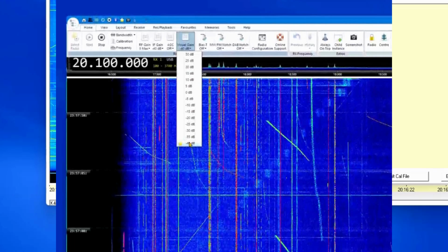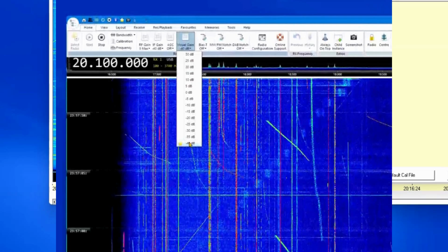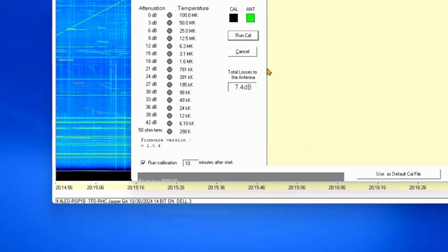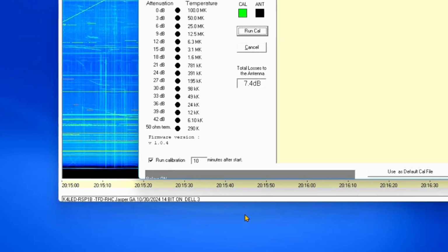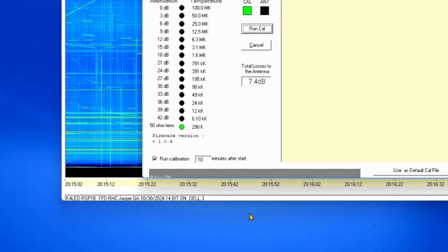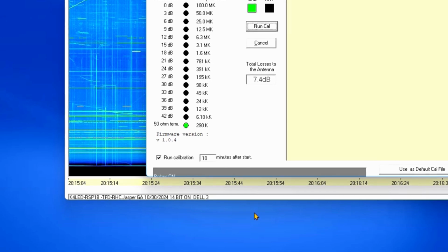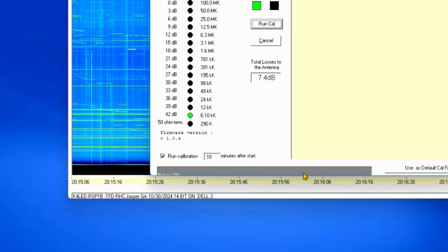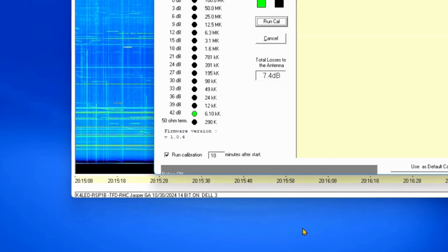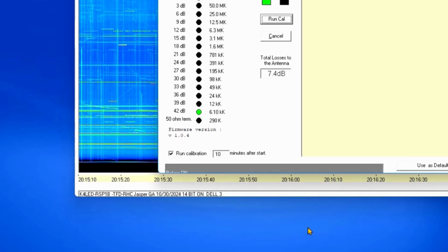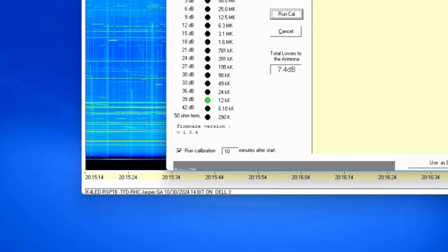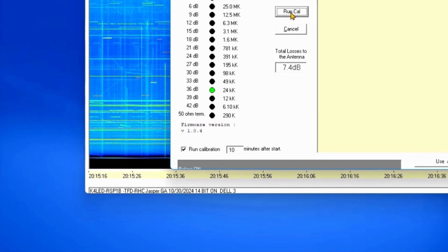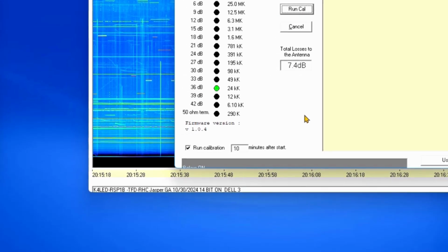First, only concentrate on the bottom left corner. Adjust the two settings, SDR Console RF gain and IF gain, to move the bottom left of the plot line into the bottom left corner as close as possible. In RSS, again, click the Calibrate menu, then run Cal. You may need to run the Calibrate menu plot several times to get it as close as possible.